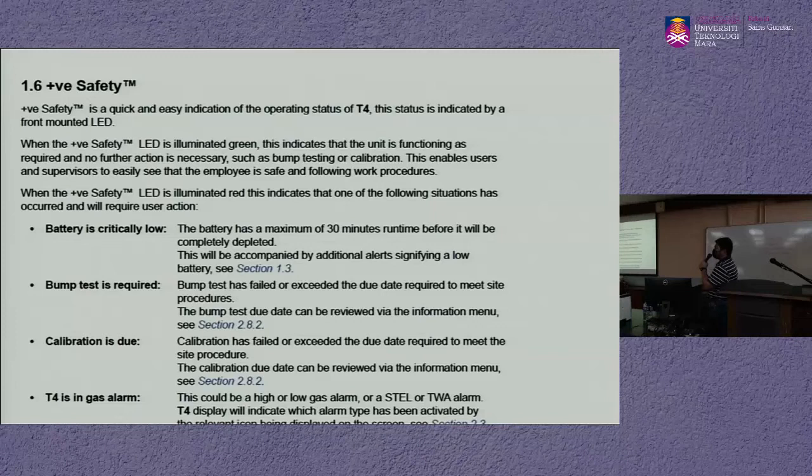So kalau contohnya it's not blinking green while you are not charging, then it means that it requires a bump test ataupun is due for calibration lah. Okay, this enables users and supervisors to easily see that the employee is safe and following the work procedures, because usually when workers gunakan gas detector within the work site at oil and gas industries, it's usually a requirement for day-to-day job lah, where you require this equipment to be used inside.